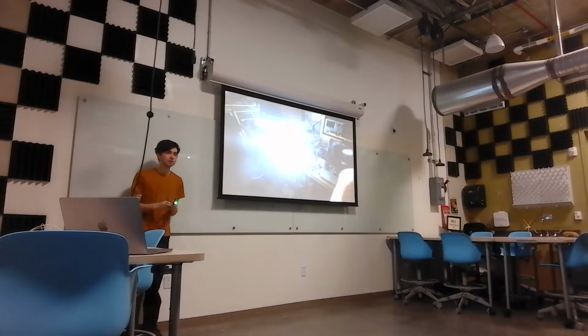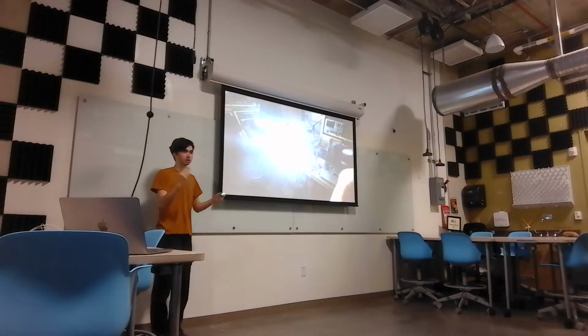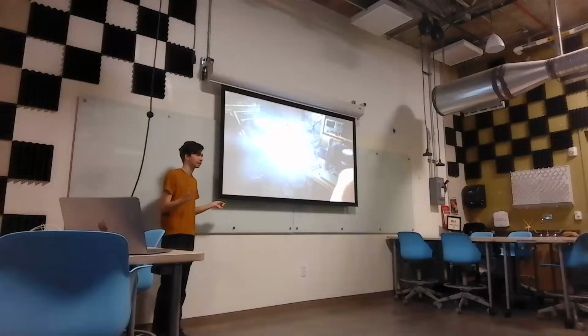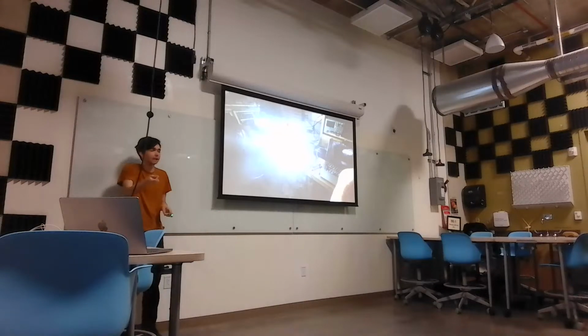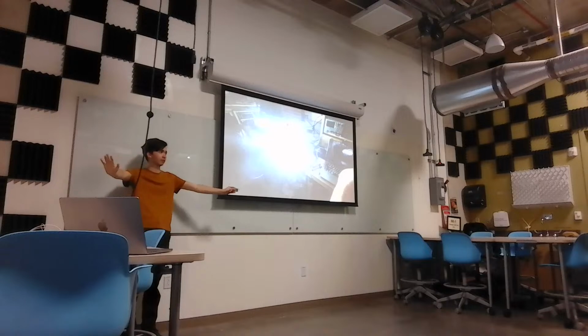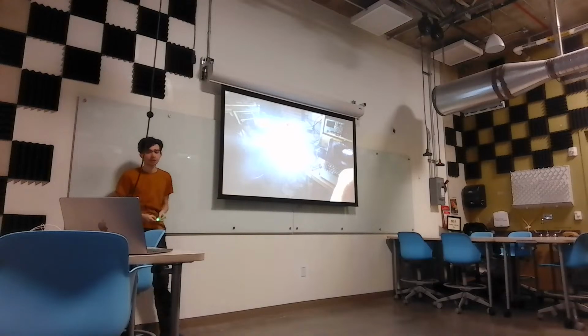That's the feedback loop. So that whole thing of it moving when I was changing the height of it, code was doing that. The Rust was saying, we got a new current. It's too high, decrease the duty cycle. So, right, and that's why the LEDs were remaining at a constant brightness, the current maintained. Everyone understands that, right? We're all following that? Okay.